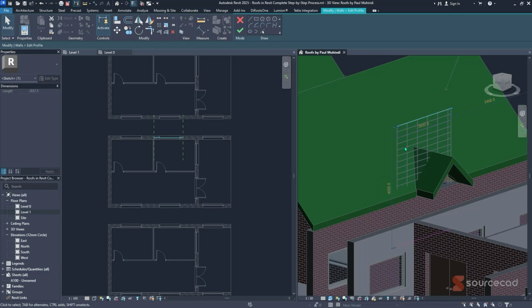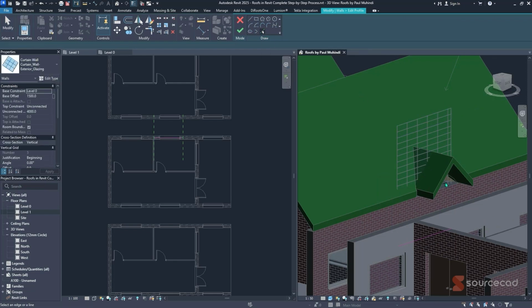For my case, I can first select that, and then try to pick my lines around here. My first line can be there, my other line can be there, and my final line can be there. For this one, I'll select it and delete it, and then I'm going to use trim or TR, select that, then select that and that, and just like that, it's finished.